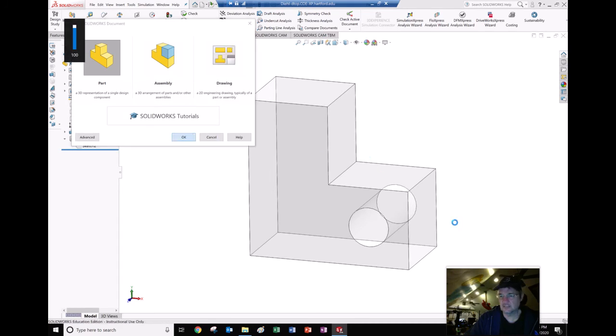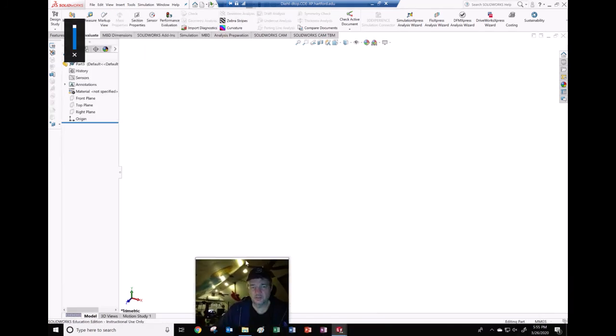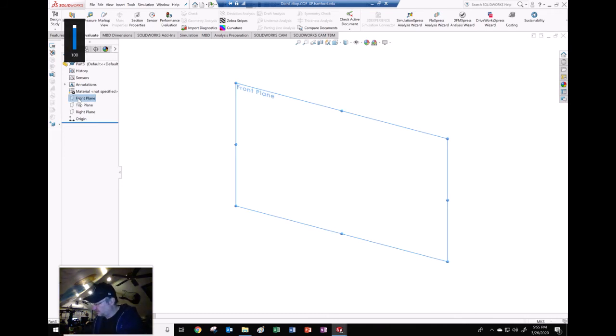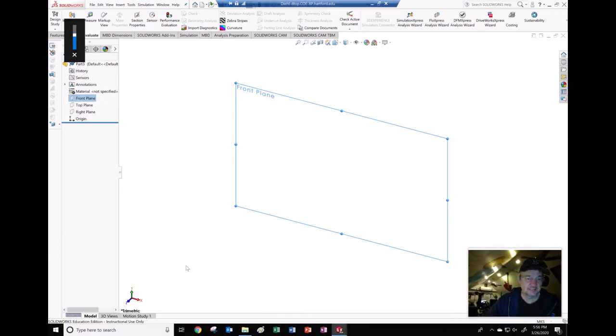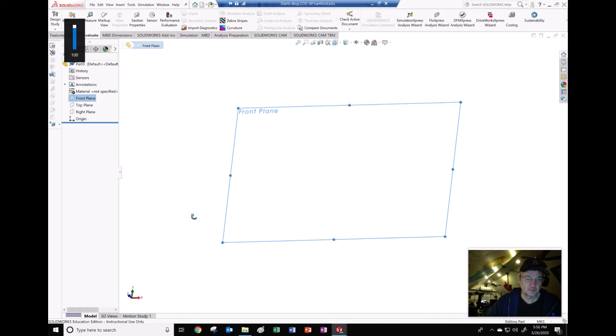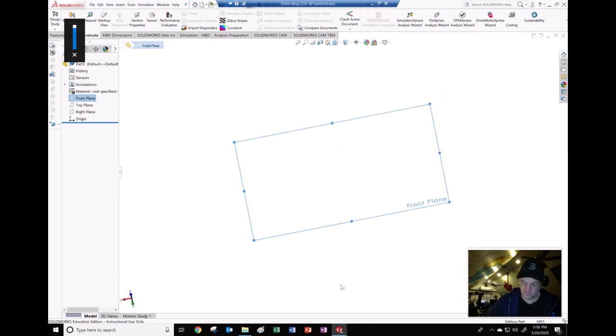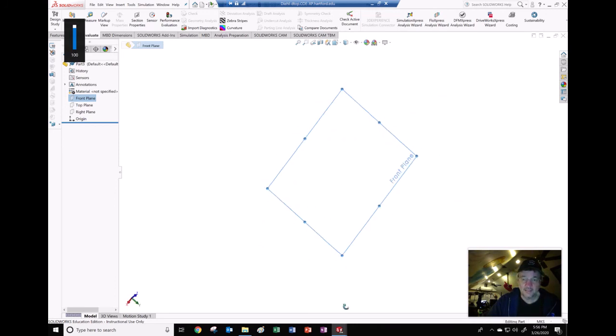But I set this thing up and get a new part. And do I want to make millimeters? I think I want meters. So let me change the units to meters. And let me take a look at what the orientation is there. I'm looking down the z-axis. And now I put my picture in the wrong spot again. I'm looking down the z-axis here. So I'm just going to turn this thing around here. Orient this. I want to draw it in the YZ plane right here. Okay, so here's how I want to draw it, like this right here.